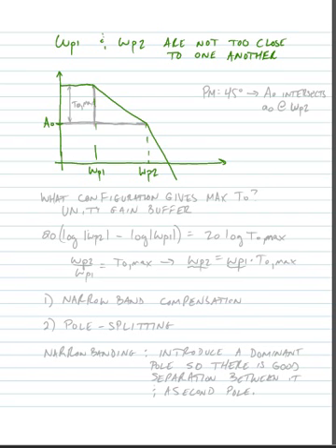If we set our closed loop gain such that it intersects the open loop response at the second pole frequency, we will get 45 degrees of phase margin. As we said before, 45 degrees of phase margin corresponds to the fastest settling time.